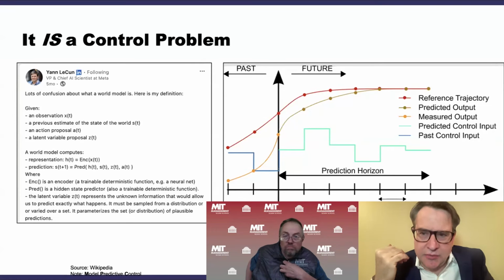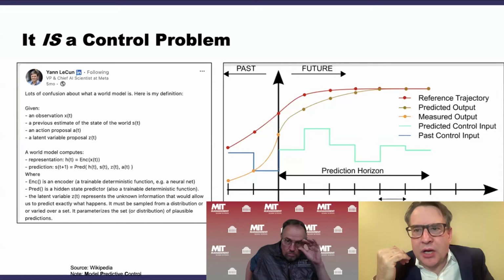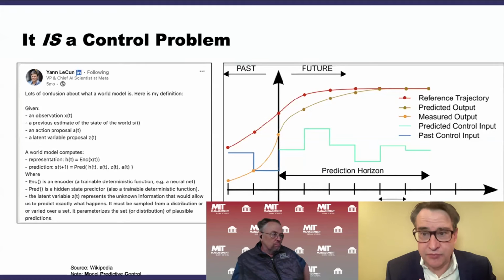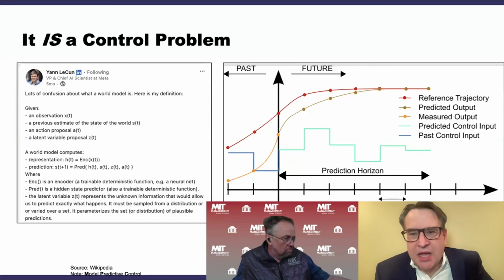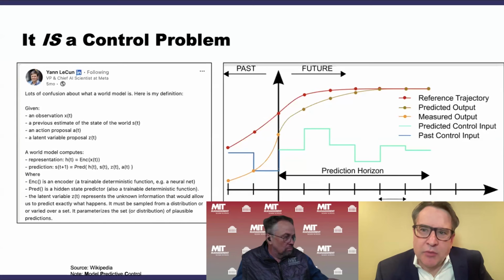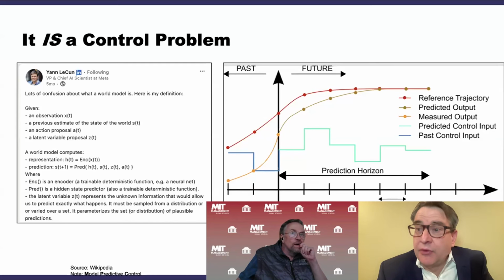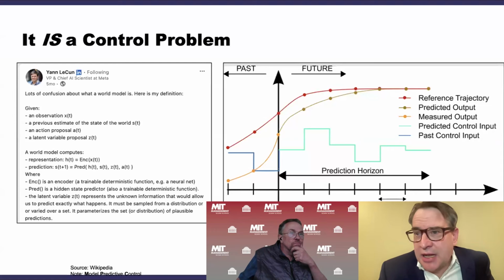The second is we need some type of model, right? And fortunately, we're in this era where the mathematical models we'd like to use are not only fairly well understood, they're also widely available, and we have the computational power to do it. The last is data. And one of the most fortunate things of where we are in Industry 4.0 is in the last 20 plus years, the cost and quality of sensors has dropped 3 to 4 orders of magnitude. So what would have cost me 15 or 20 years ago to put in a real-time vibration sensor, several $1,000s, and I'd have to wait 4 weeks to get a control engineer to put it in for us. And then we would probably spend a week or 2 tuning it.